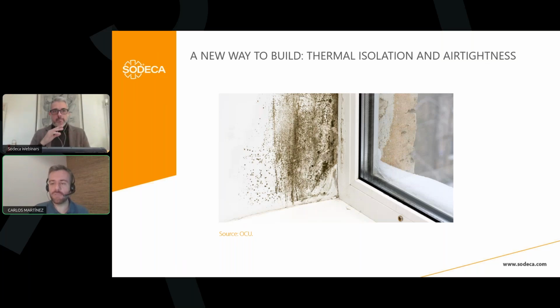When unintentional natural ventilation is eliminated, okay, we increase the energy efficiency of the building, but also pollutants begin to accumulate indoors. We need to bear in mind that we are exposed to several pollutants that are generated inside the buildings just because of human activity.